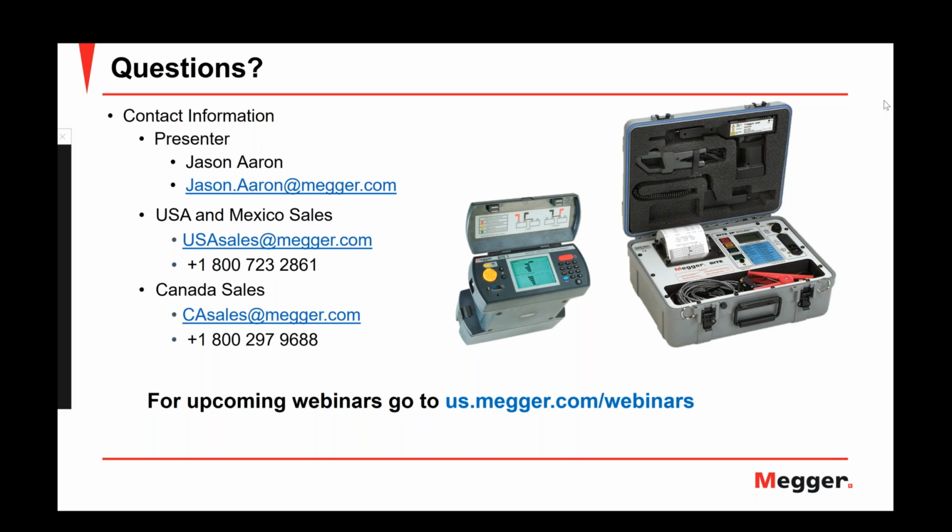All right, thank you. Sanket, can the byte 3 tester measure multi-tap straps per cell impedance like the byte 2P? Yes, and again, in this aspect as well, the instruments function differently. Now with the byte 2P, you have a CT which you wrap around multiple straps, and then you let the byte 2 know how many straps you've wrapped it around, or you introduce a certain multiplier so that the software calculates the resistance accurately. But with a byte 3, you do not have a CT.